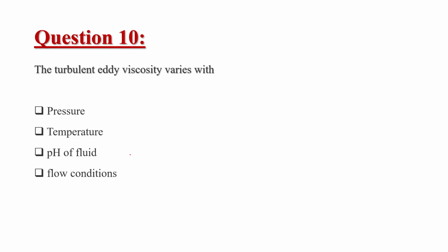And this y, if you can see the coordinate system is here, so the y will be changing from this point to this point, that is from 0 to h. Okay, so the integration of y will be changing from 0 to h, and here also 0 to h. That means this will be nothing but equal to h. So we have 1 by h into integration from 0 to h of u into dy. Correct?